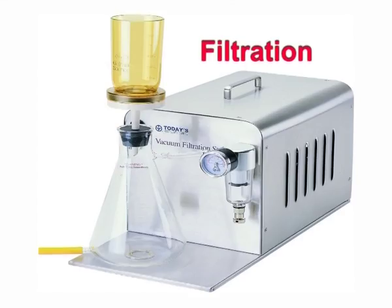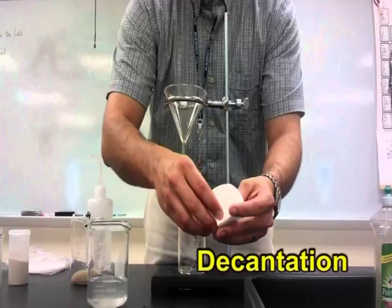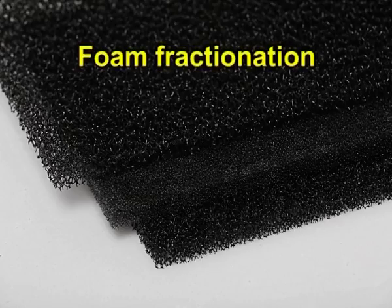In most cases, however, the separation methods used are filtration, centrifugation, decantation and foam fractionation. Where the required fraction is in the cells, then much of the impurities are removed with the filtrate after the cells have been isolated. The various methods used in solid removal are discussed below.